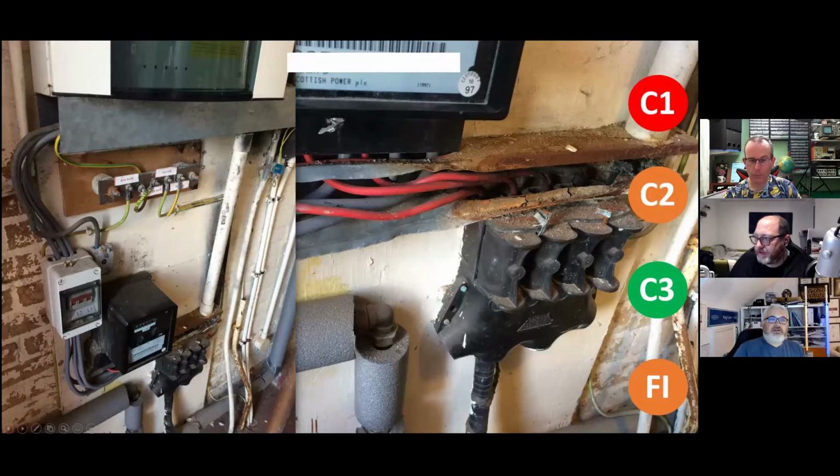I'll tell you one thing I've noticed while everyone's doing this. I reported a DNO cutout with a hole in the top. They now fill them with putty rather than a plastic insert and a screw to tighten up. They get an insulating putty, mold it in their hands to activate it, and stick it in the holes. And I thought, you lazy bugger, just change the cutout. But hey ho, anything to reduce risk to the operatives, I suppose.